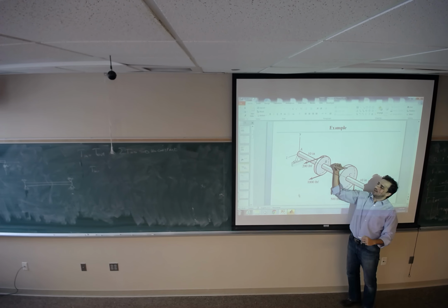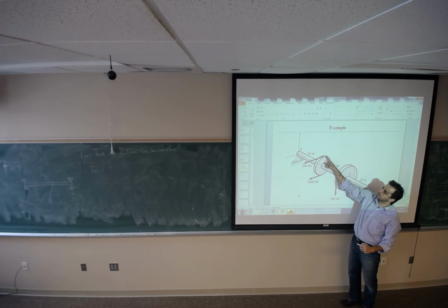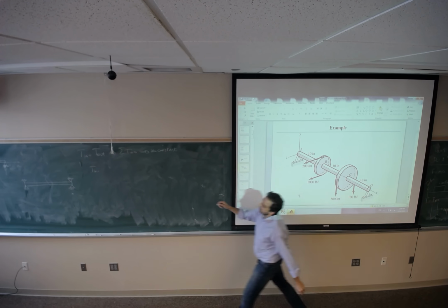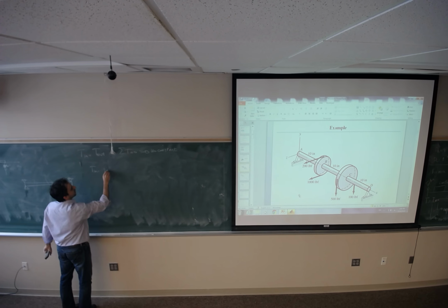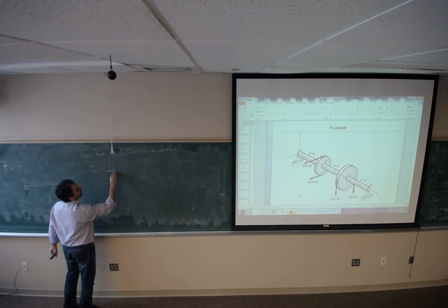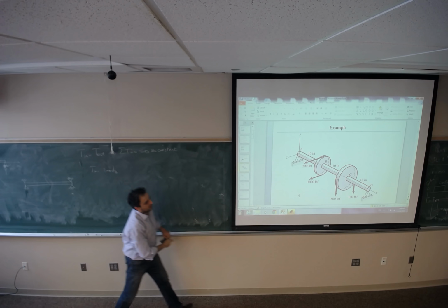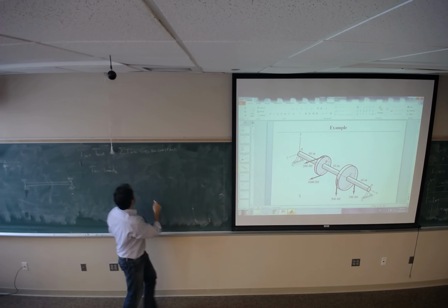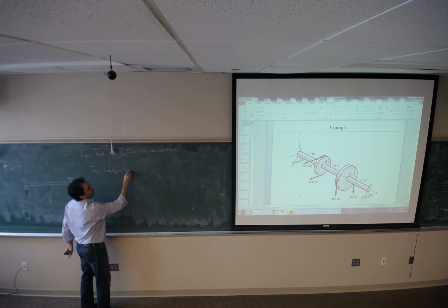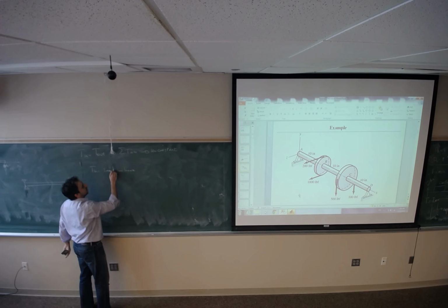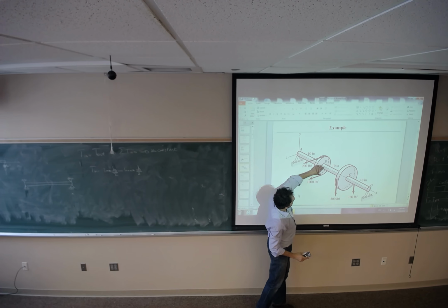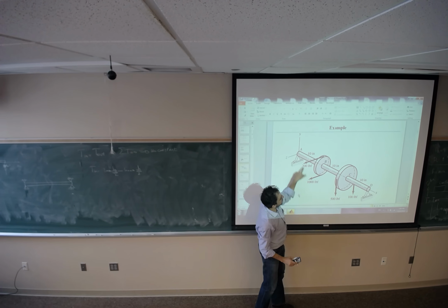It's going to rotate in this direction, which is the positive direction of X. So T in is positive 200 times the diameter of pulley B. This 1000 is making rotation in the opposite direction: 1000 times half of the diameter, which is the radius. Force times distance is making rotation.